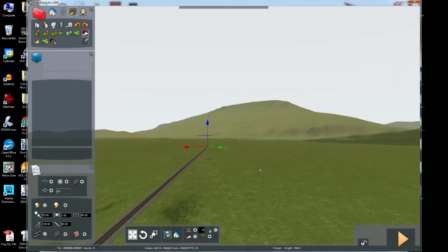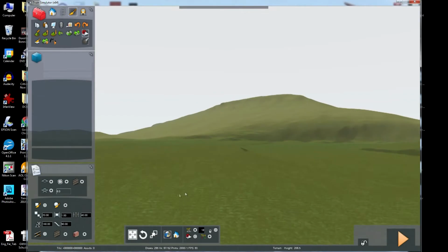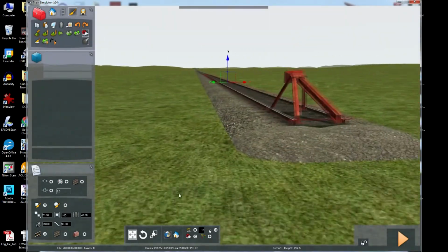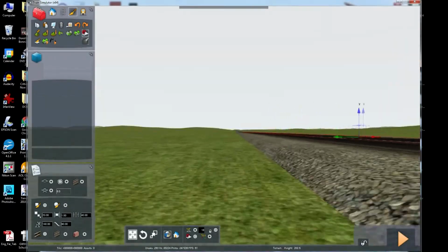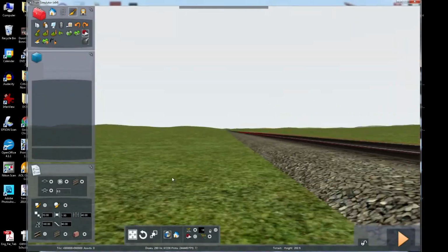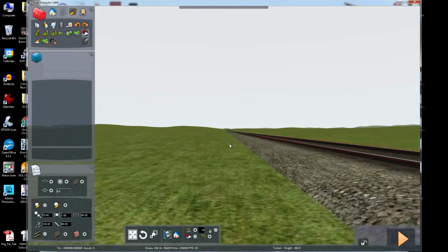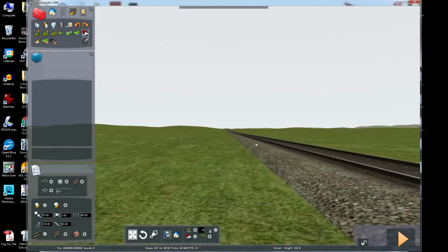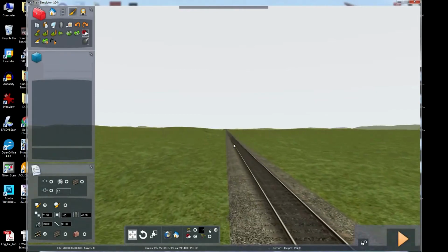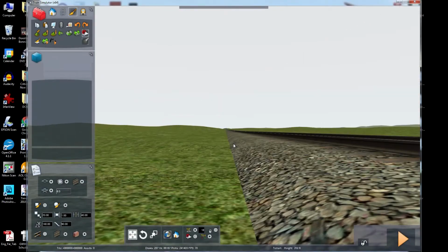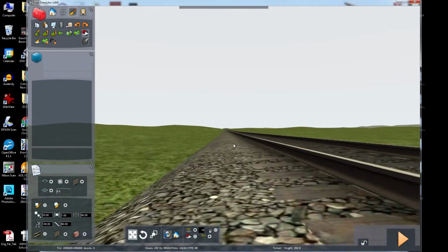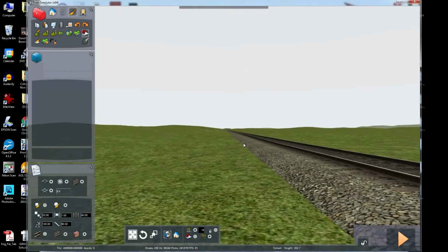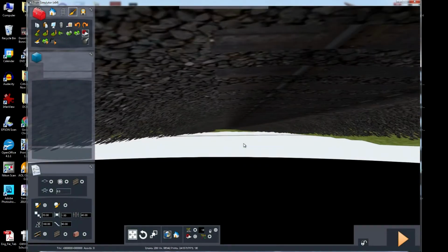So we go back to the beginning again, and let's follow our track. We'll actually be able to see the changes in these when they get more abrupt. But you can see out in the distance that there's grade. Here's a grade change. Here's a more substantial grade change coming up. The way you can tell that is to eyeball it at rail height. You can see the rather abrupt changes.